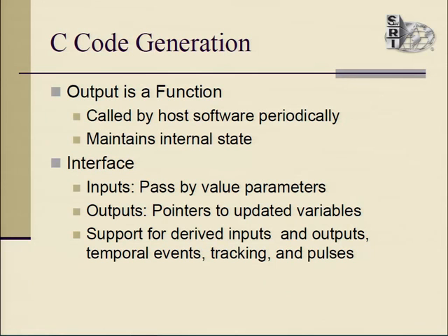Inputs to the module arrive as pass-by-value parameters to the function we create. Outputs, the module will keep track of all its outputs internally, but it will also write those output values on every call to values that are provided as pointers to the function. And we have support for all of the timing features. Those are all captured internally with static variables within the function.